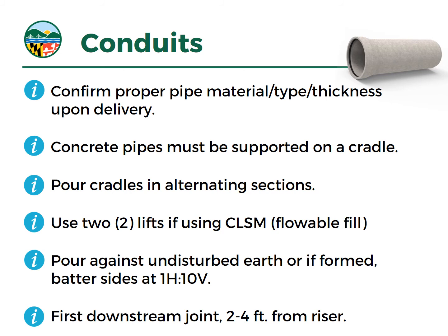There's often plant markings on the pipe that indicate the type of pipe and what the specification is. It's easy to compare to your project specs, but you don't want the wrong pipe delivered accidentally, or somebody thinking they can get away with putting in pipe type A when really pipe type B is what's specified, because they can look similar. Sometimes it just comes down to the joint profile and details.